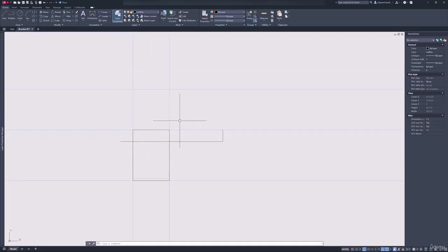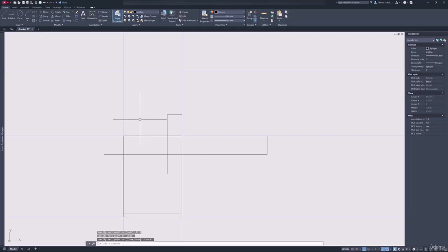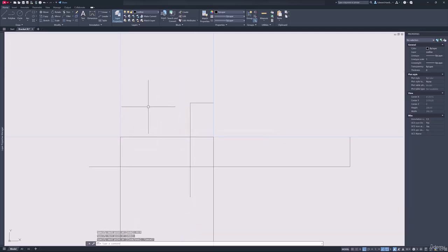So again, I'll go ahead and press L, select line, snap to here, bring this over, and let's type in 22.5, enter. And then just drag it down like this, a left click again, and then go ahead and press escape. Okay, so there's two ways of doing this now.